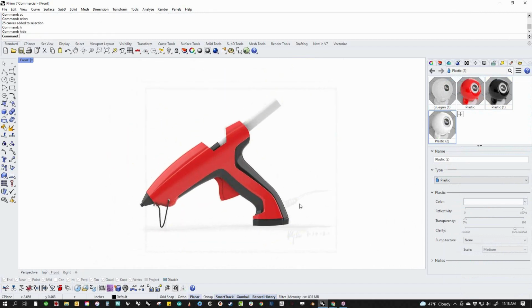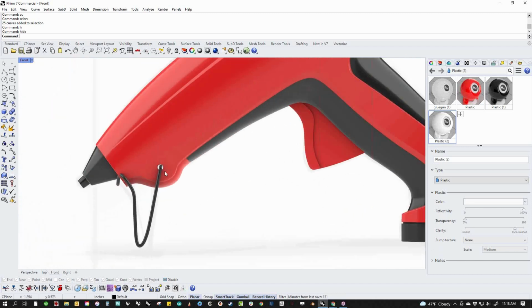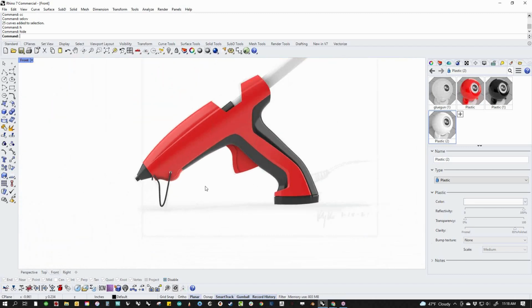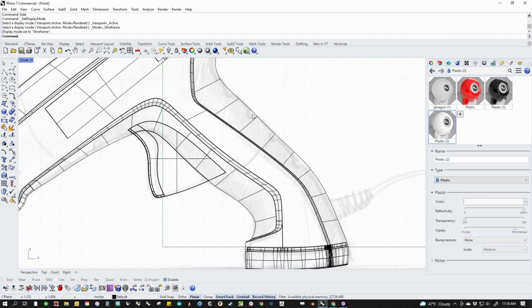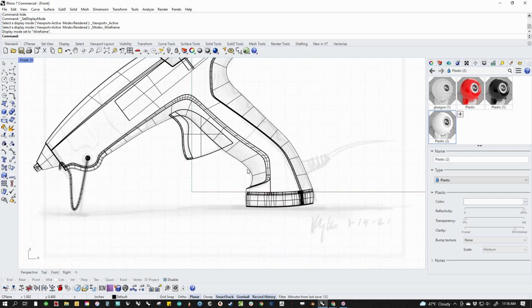Have our curves. And then essentially if we wanted to get into this further, we'd build the chord and all that kind of stuff. But I think I'm 18 minutes over and I apologize for that. As it sits right now, this is probably where I'm going to stop. If you wanted to add the additional details on this, these little cutouts and things like that, I would just do those with pipes. I would just make a tube and Boolean those notches out of there. Same for here, top and bottom.